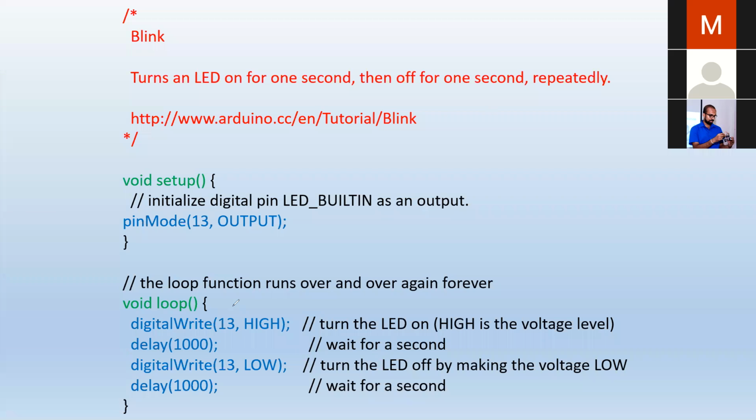If we had used delays there, imagine what would happen with a 5-second delay when you want to apply brakes. It is not going to do anything. So there are other techniques where you can ditch the delay, where all the other things turn off and the braking function turns on. Using the delay is all right, but there is an example where we blink an LED without the delay. When I get to that, I will explain a bit more.